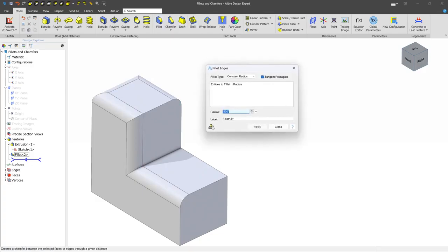The next thing that we'll talk about is a fillet option called tangent propagate. And what that does, and I'll demonstrate by turning this 3D preview off, is we'll select this particular edge and we'll turn off tangent propagate. So what this is doing is when tangent propagate is turned on, it basically says, does the edge that we've picked have a tangent relationship with any other edge? And in this case, we do, right? We have this corner round. And so if we were to turn this on, it's also going to go there.